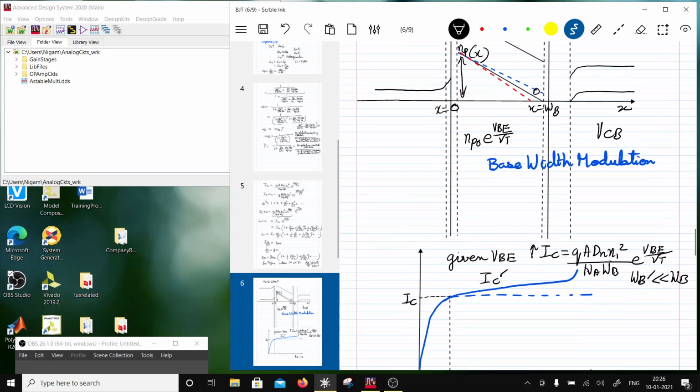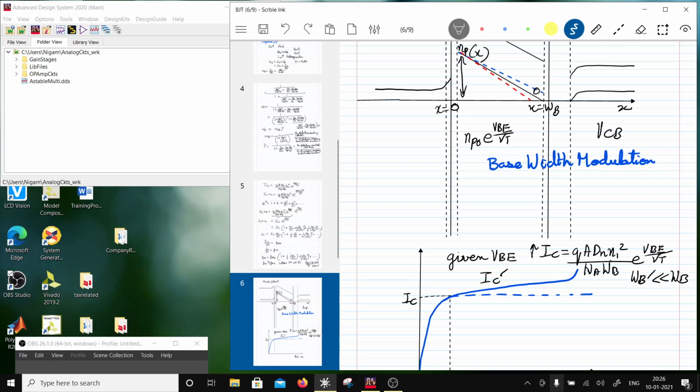So diffusion capacitance is because of the, so for example, if you forward bias a diode, right? So when you forward bias, the majority carriers are going to sweep in and the depletion region is going to vanish. Minority carriers are also going to go up, right? So that's what we have seen in a p-n junction diode, and it takes a diffusion length by the time it decays to the same as the bulk, right? So now